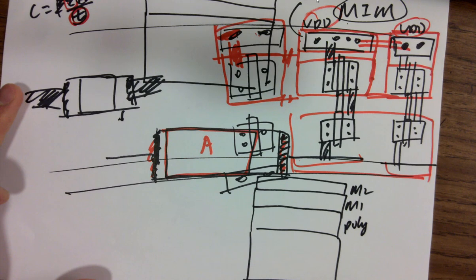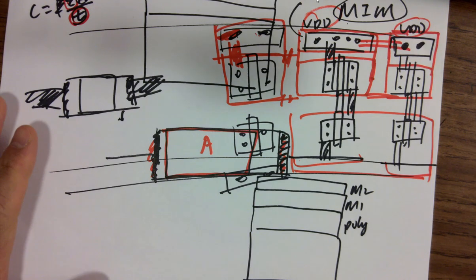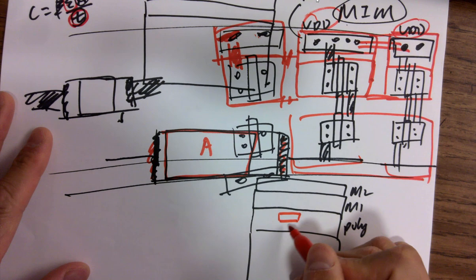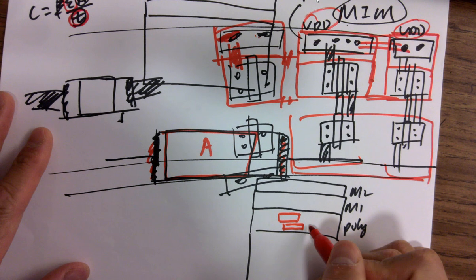There are actually 2 poly layers available. If you take a closer look at your Electric VLSI library on the left hand side, you will be able to see that. There are 2 different poly layers, but only poly 1 is being used as a gate. Poly 2 is somewhere else. You never used it, but it should be used for capacitors. So there's a poly 2 on the top and poly 1 at the bottom. That's P1, that's P2.